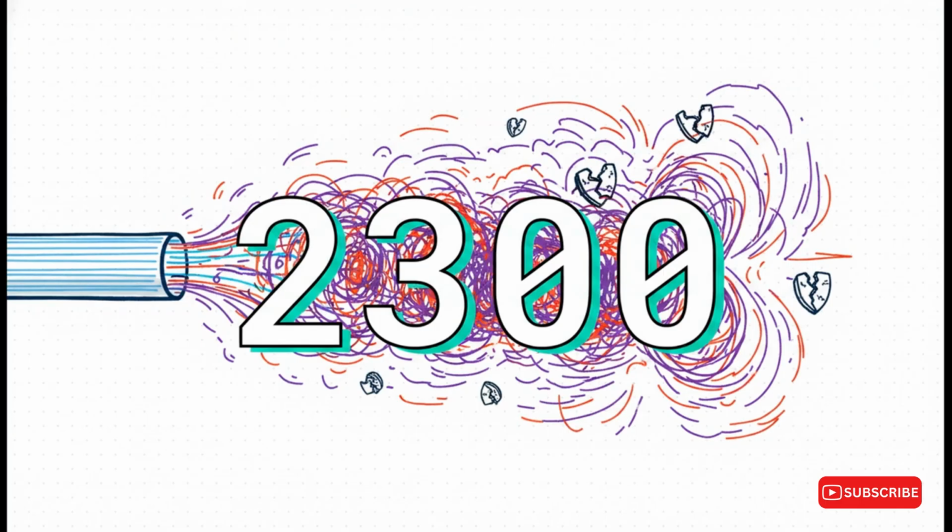In a standard pipe, when the Reynolds number hits a critical threshold of right around 2300, that's it. The fluid's inertia finally overwhelms the viscous dampening. The shock absorbers completely fail. Minor surface ripples suddenly amplify and literally shatter those symmetrical layers into a spiraling mess of chaos.